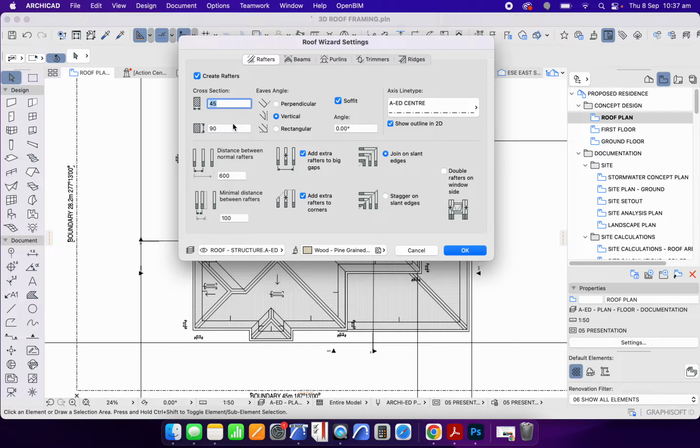I would generally, with new builds, only use a conventionally framed roof if I wanted to expose those beams. And that would generally mean that I would have a raked ceiling, not a flat ceiling. Of course, there are alternatives to this. We could have a scissor truss where we actually have a raked ceiling as well. And we could be using a conventional roof if it was a traditional type of roof, even if we're having a flat ceiling. But the rules tend to stand.